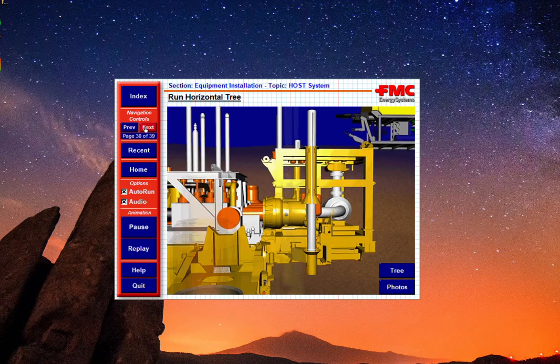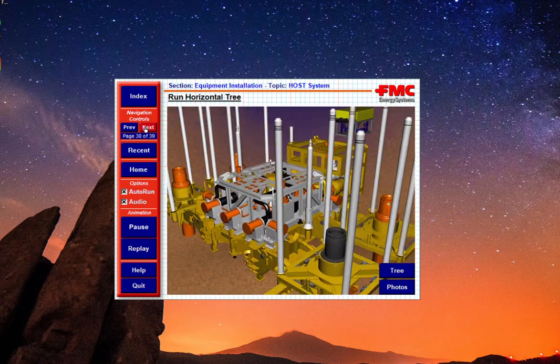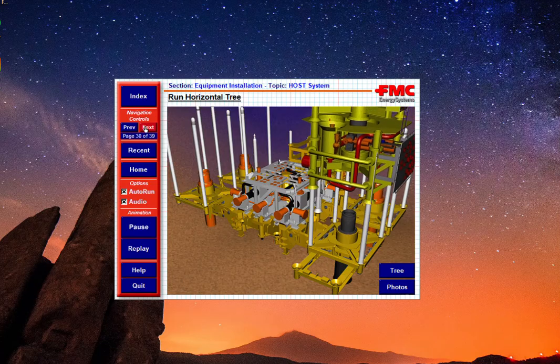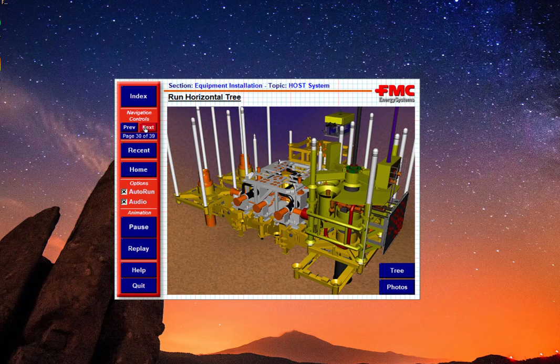The Terra Nova project features 5 by 2 inch, 6,650 psi horizontal subsea trees. The tree is installed using drill pipe and a standard installation tool. An associated workover umbilical termination head is also run with the subsea tree during its installation.